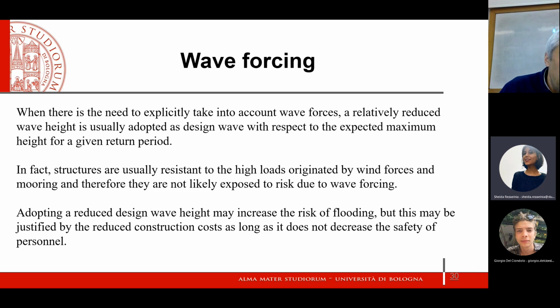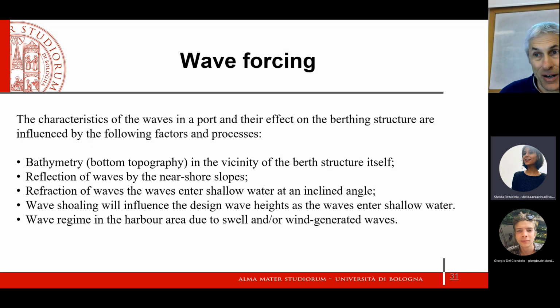So we can also take the risk of the berth being flooded, and we have to take into account that if the berth is flooded, of course, the loading and mooring operations may be interrupted, but it is not really a big problem. So the moral of the story is that when you already designed for wind forcing, for wave forcing, you may, in a way, decrease your safety factor, always by looking at the local rules.